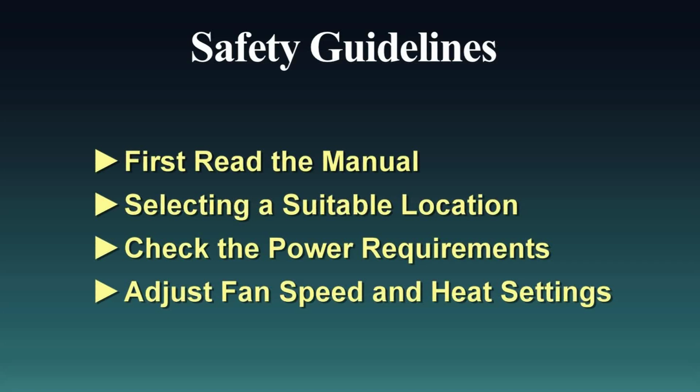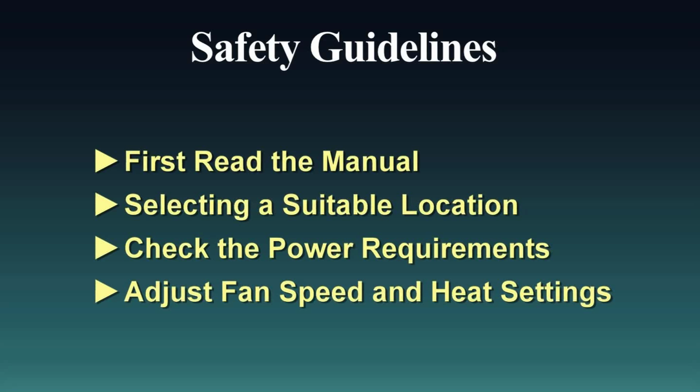Now, selecting a suitable location. An appropriate location for the device needs to be chosen to ensure that it is placed on a stable and flat surface, away from flammable materials such as curtains, furniture, or papers. We should maintain a minimum distance of 3 feet from any combustible items. Check the power requirements. We need to verify the power requirements for our electric room heater and should avoid the use of extension cords or power strips.